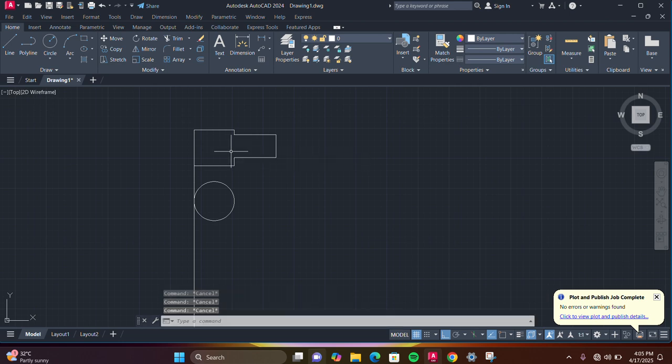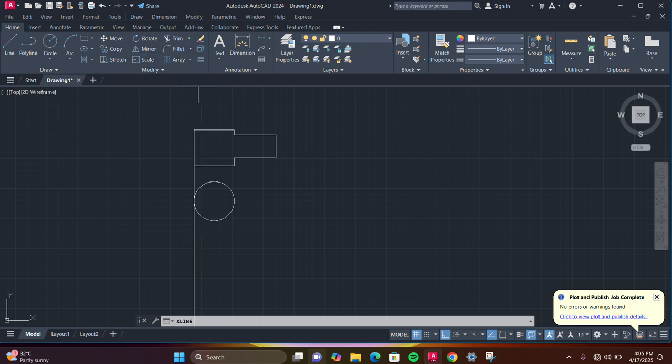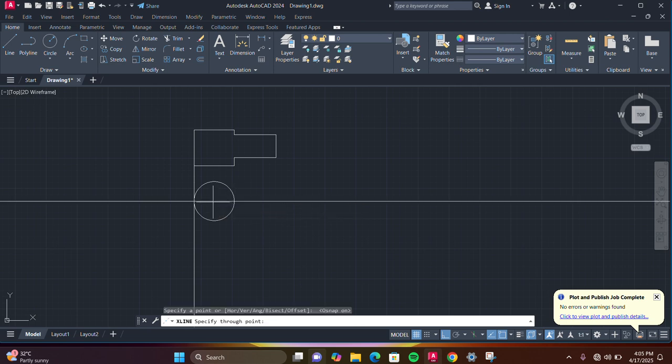So now, what next? You need to draw the plan for your horizontal cylinder. So you can pick your construction line, pick up the horizontal line here. But before that, you can on your object snap again. Left click on this. So now you can offset upward by 19, downward by 19, since it is the same cylinder, which is horizontal.